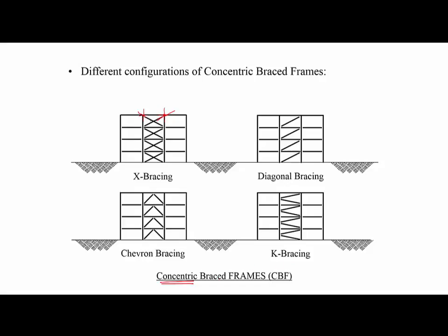In the X braced frame, if your loads, for example, are coming from left to right, then these members are going to be in tension. These members are going to be in tension, and the other braces are going to be in compression.